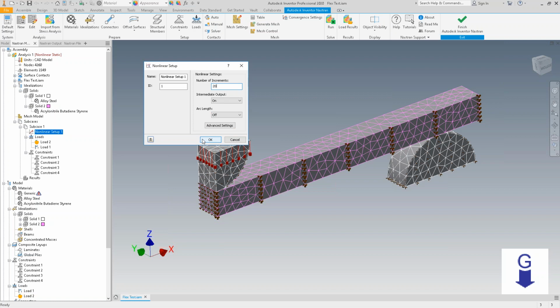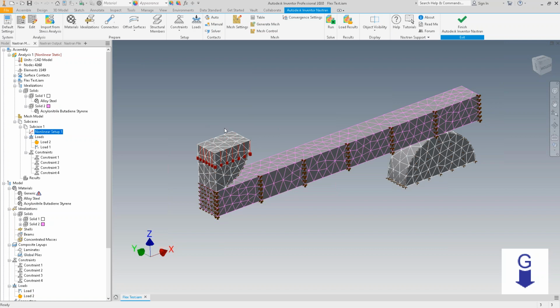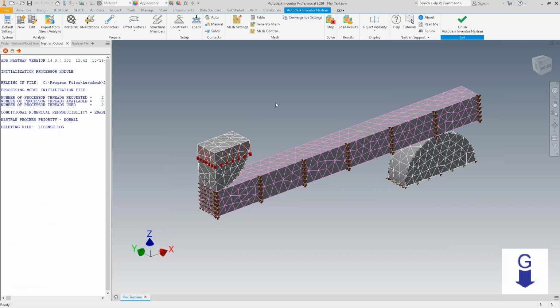That's the big benefit of running nonlinear, whether it's with materials or deformation. This is a big benefit to where you can actually dive in and see exactly when does the material exceed that stress amount. And that's what we're going to be able to do. The downside with any kind of nonlinear analysis you run, and I don't care who you run it with, they're going to take time. You've got a lot of math going on here, a lot of things happening in the background.